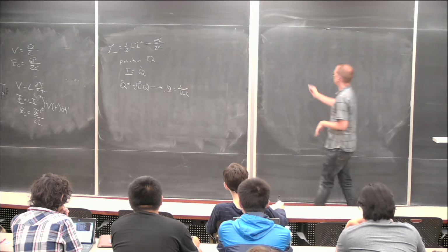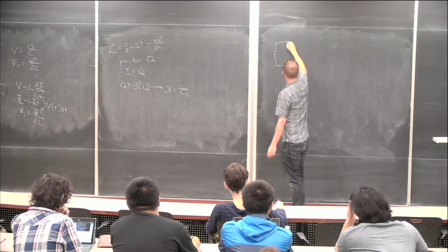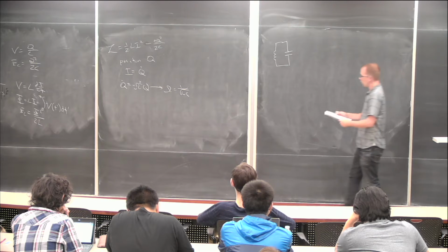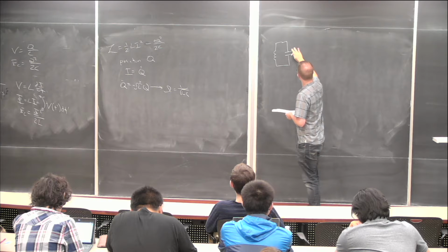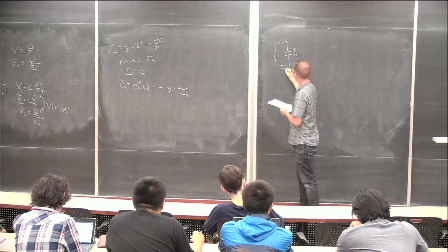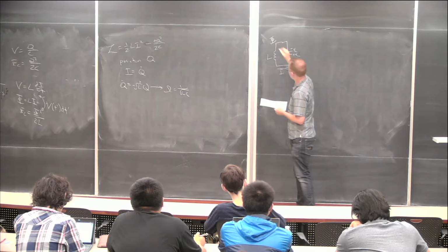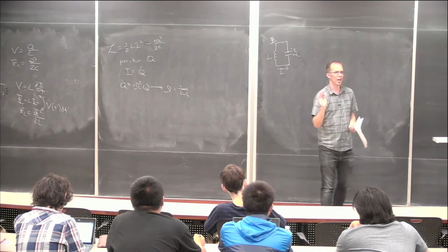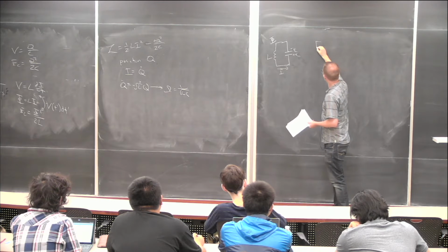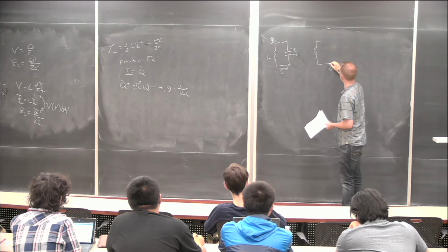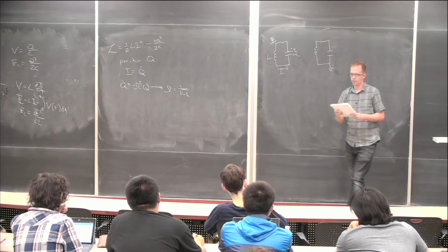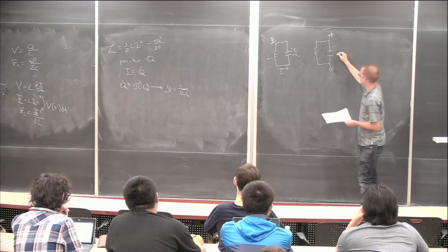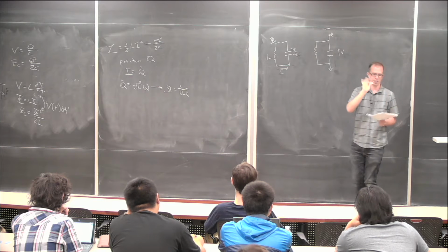So if you've seen this before, we're going to ignore it and do things a little bit differently, and you have to be ever so slightly careful in defining your signs. A typical circuit that you quantize would have an inductor and a capacitor. When we do this formalism, we define a charge plus Q and minus Q, with current flowing this way, an inductor here, and that gives you a flux up here of phi. You can similarly define, by gauge invariance, any one part of this to be a ground node, and we can work up from there to find actual fluxes, which are kind of like voltages. And you need to define a direction in which you move in order to get your fluxes, and I'll tell you exactly what that means.